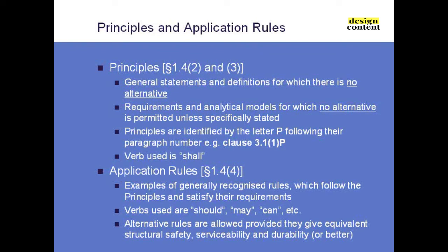And all principles should be marked in that way, but there are still some typos basically in the Eurocodes, and there may be some P's missing in some places, possibly. So the other way you can spot a principle is the verb used is shall, a very high degree of compulsion. You shall do this. It's the same sort of system that the Highways Agency did with all their BDs, changing the shoulds in the BSs to shalls in their BD. You've got no choice, you've got to do it.